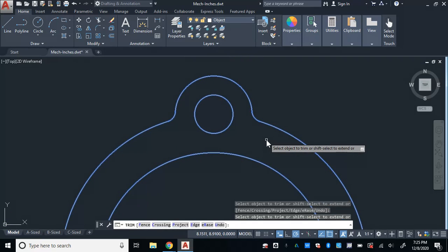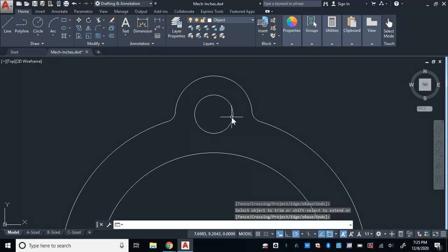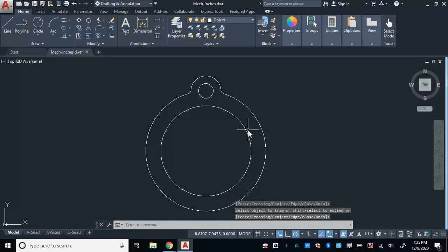So there we go. There's our fillet on either side. And we have our outer part of the gasket. We have our hole pattern for the bolt. I'll hit enter to finish the command. All right, so now I finish that. So that's just the top portion. Now you have 5 more to go around.